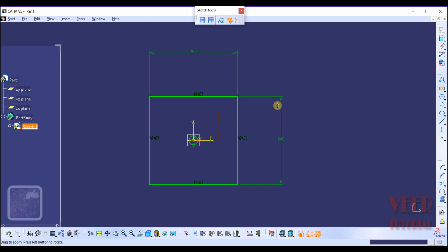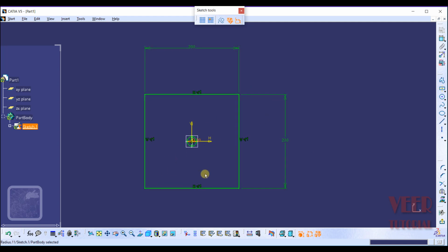And then we need to make this cutout part. So for this cutout section we need a center line. So we can draw a line like this for reference, or before this we can also start with creating a rectangle. So I draw a rectangle, I take a corner rectangle and draw a corner rectangle like this.